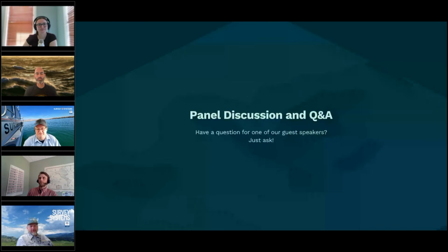There's also a function inside of our data collection package called BAGs. That's where we do bathymetric grids, and we put metadata into it, like total propagated uncertainty, quality control, the sensor used, and what the settings were on the sensor when it was collected, and then it creates what we call a BAG.